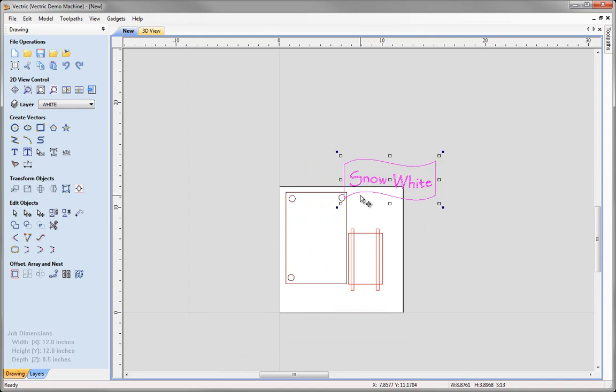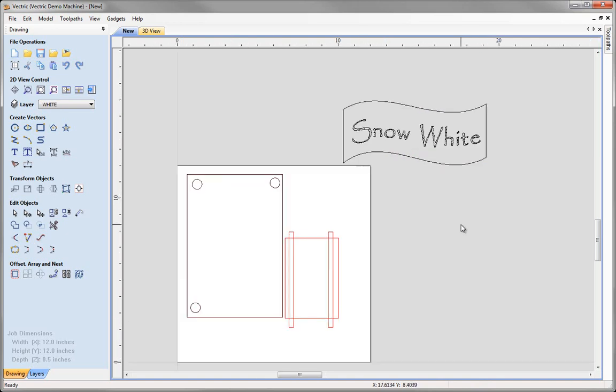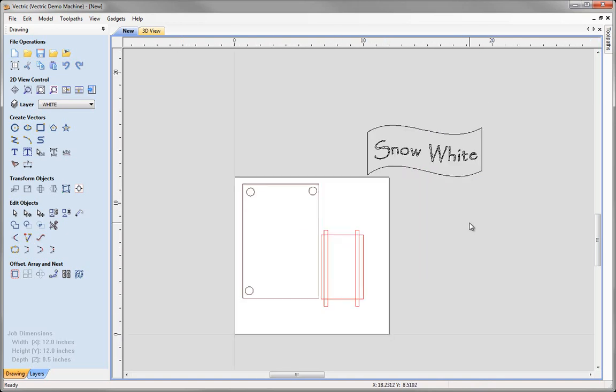Obviously, if we imported this file directly through the method first discussed, then the software would automatically find the bounding box, it would offset the material block to exactly match, and you would definitely see the file that you just imported, albeit that it would have a massive offset in real units to the origin of the material block to start with. So that's the first gotcha to watch out for. Now let's have a look at the layers that have come in this case.